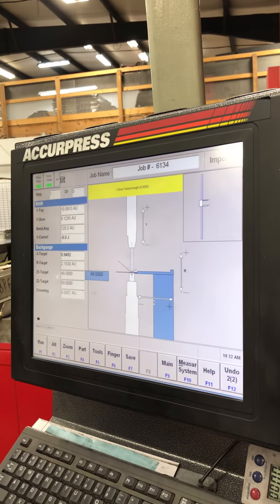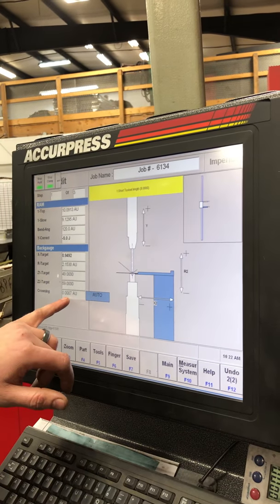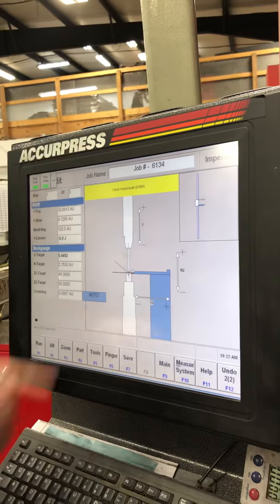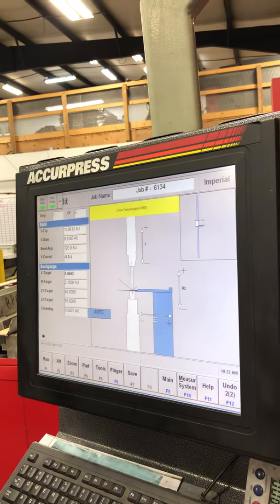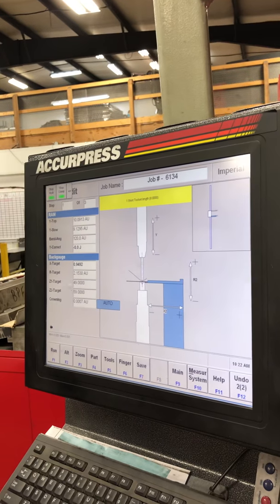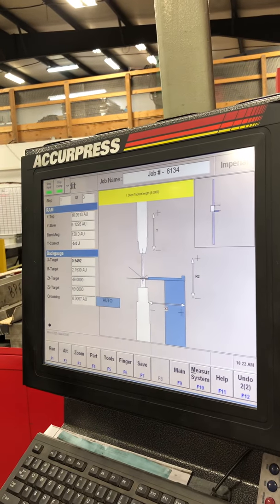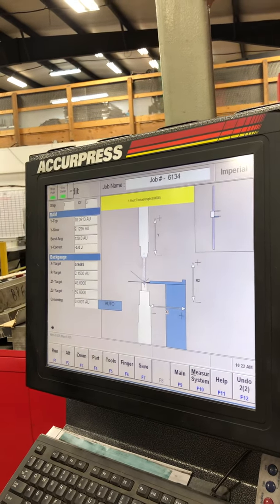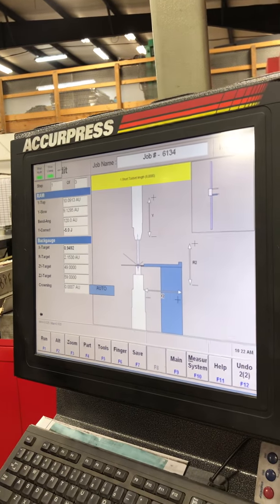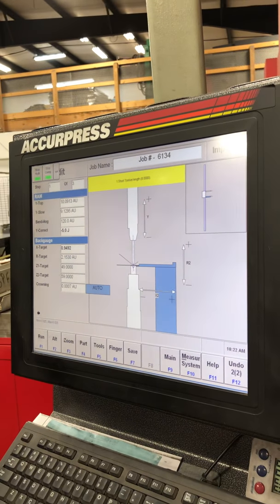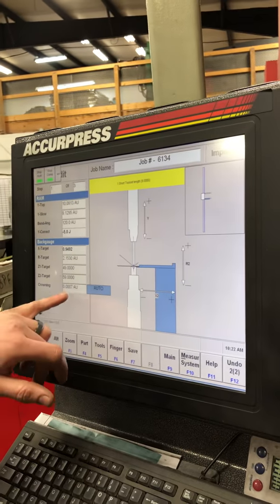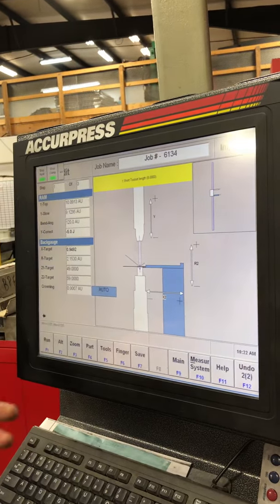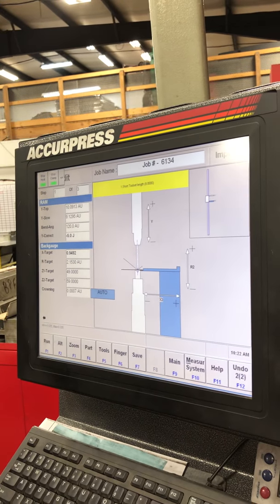It works really good. Now, crowning is going to be this little motor that's on the side, and the crowning takes the center of our bed and it's going to push the center of the bed up. So if you're forming long parts without crowning, you might shove it in there, step on the pedal, you're going to pull it out, you're going to be looking at a banana. Right. So the crowning allows us to push the center of that bed up to keep your bed nice and straight. And it's all calculated. Yeah, it's all calculated. The machine does it, but we can adjust that too if we want. So if it doesn't look good, we'll up the crowning on it to level the bed up.